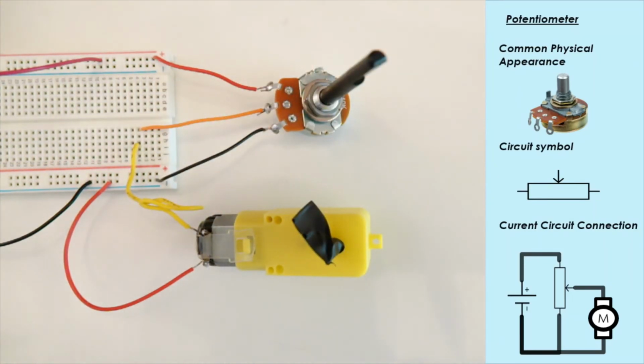So before we get into all of this, let's first have a brief discussion about the schematic on the bottom right. What we have here is the positive end of our battery connected to one terminal of our variable resistor. The other end of our variable resistor is connected to the ground of the battery, so we have this loop. Now, we have our wiper pin, which is going to move up and down, and it's going to change the resistance on either side of our variable resistor. As the wiper goes up, the resistance on this lower side is going to increase.